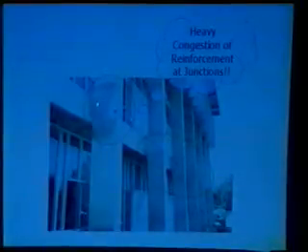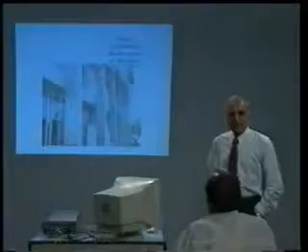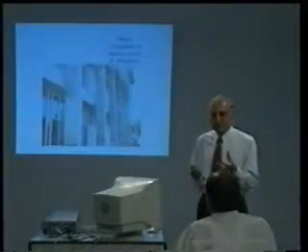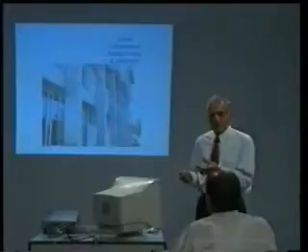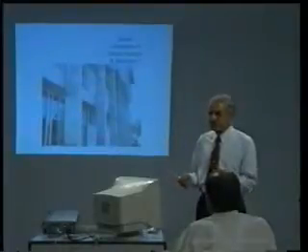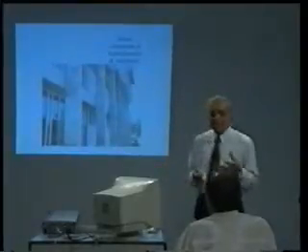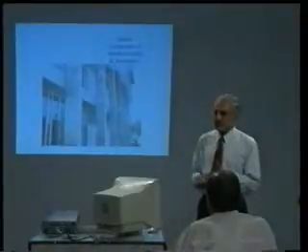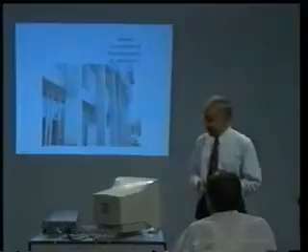If it was poor workmanship, it would be only here, but this is the thing that you observe on all these column beam junctions. So, this is the result of heavy congestion of reinforcement. This can be avoided by providing large diameter bars, a lesser number of them, grouping the bars, and also providing highly flowing concrete by using proper plasticizers and a good slump.